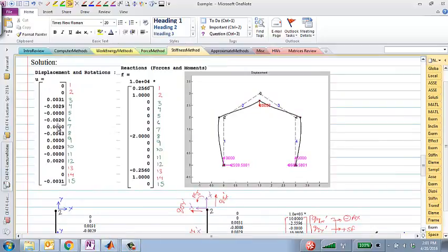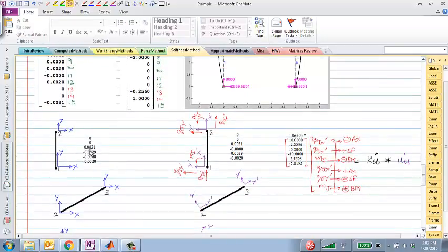Once you have the solution, pick out the element degrees of freedom, convert those element degrees of freedom from the global coordinates to the local coordinates using the inverse transformation. Take that local degrees of freedom and pre-multiply it with the element local stiffness matrix. You get the force vectors and pick out the correct components from those 6x1 for the axial force, shear force, and bending moment diagram. Make sense? We'll do that for a couple more elements, and then I'll let the program run through.